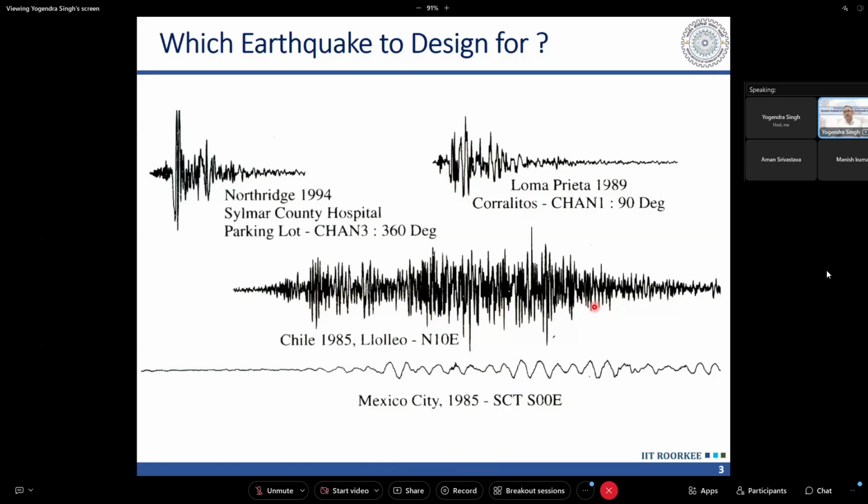If we are talking about fatigue, where the surface load is causing this type of fluctuations in the stresses, that is also causing some damage in each cycle. And if the damage gets accumulated for millions of cycles due to fatigue, we get the failure. In case of earthquake, what we get is the low cycle fatigue. So with a limited number of cycles, not millions of cycles, because the deformations are in inelastic range, the structure gets damaged or collapses with fewer cycles, and each cycle is causing damage, so damage gets accumulated. So the duration of earthquake is also very important.